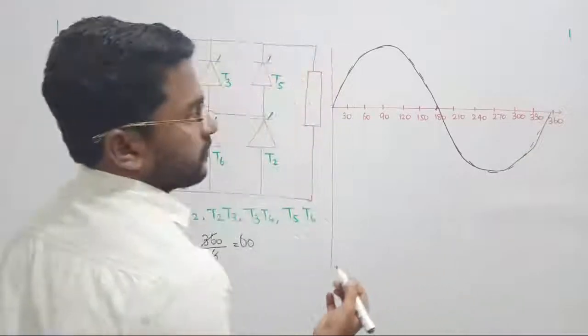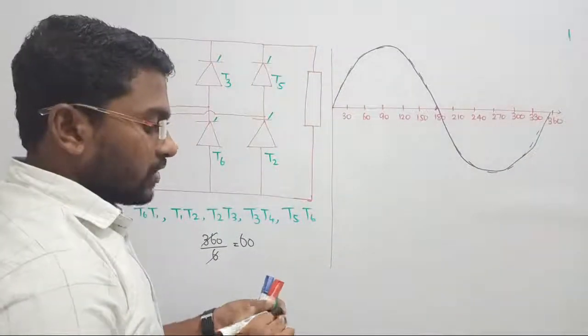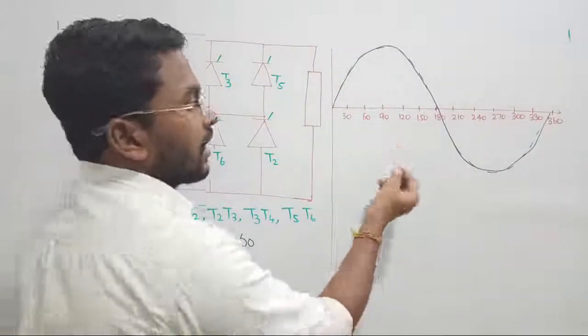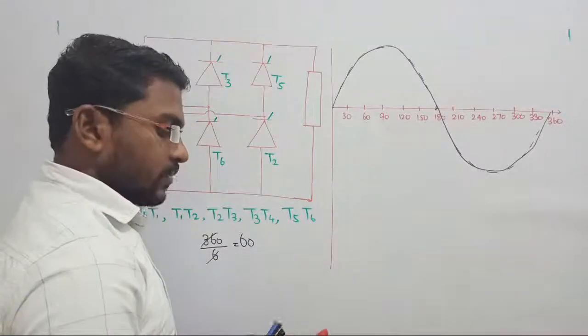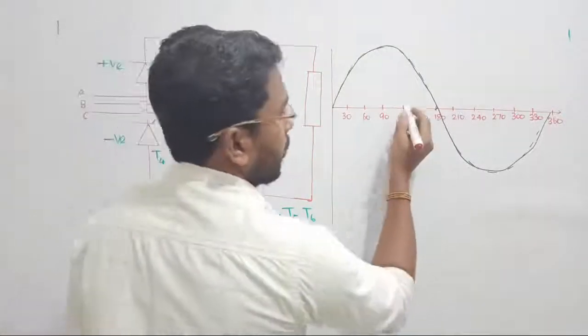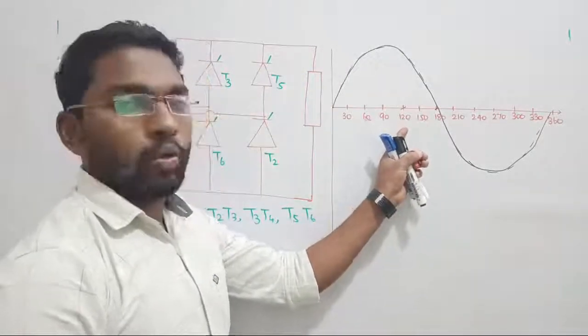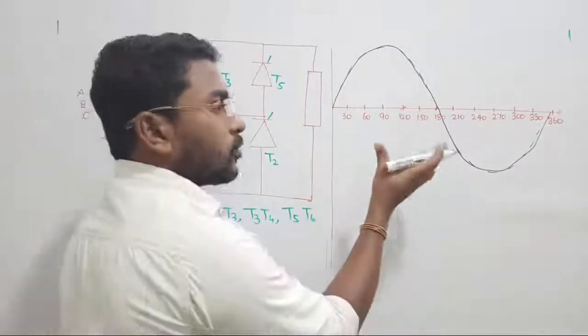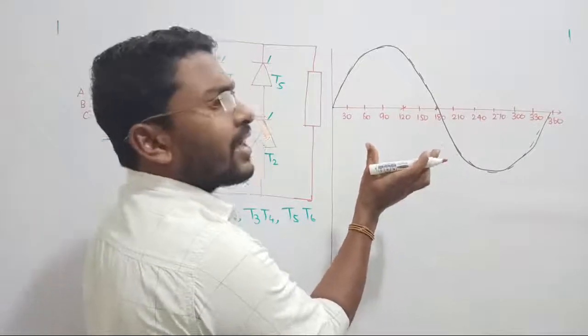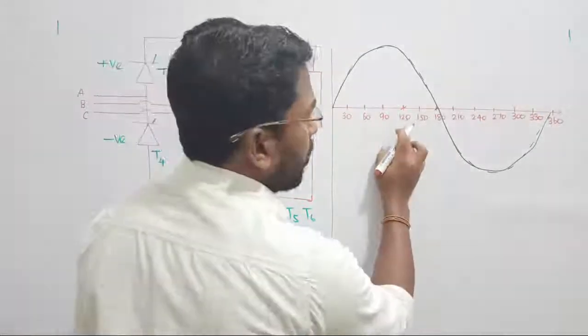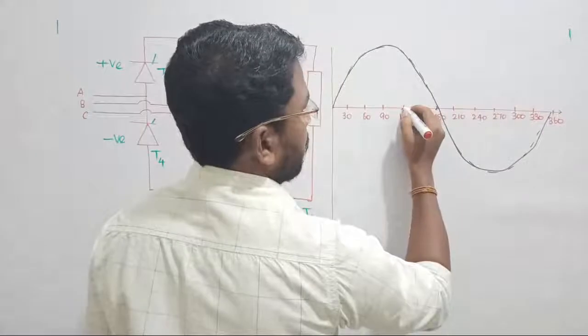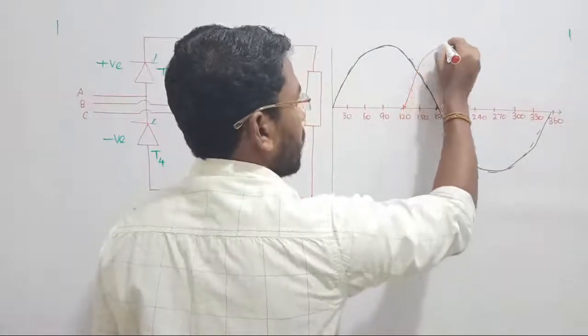Let us go with that, that is phase A voltage. Phase B voltage, what will it do? Phase B will start after 120 degree. So the displacement, phase B will start from here. Now 120 plus 180, since each and every half cycle carries 180 degree, so 120 plus 180 is 300. So it will complete the second cycle. It will go like this.